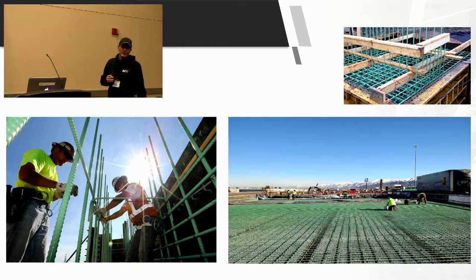Do your rebar counts on everything, so that you're not missing any. Everything may look good, but they're short two bars. Well, then it's not built the way the designer designed it, and now you're going against what the engineer of record has told you to do on the bridge, and if something happens with the bridge, it's your problem, not theirs.